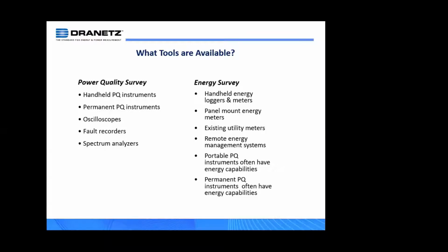And then of course when you get into permanently installed systems, now you're getting into situations where you're using remote energy management systems. And the other thing that we should note here is that we learned this in some of the early segments, that PQ instruments often have energy capabilities, simply because PQ instruments, the resolution obviously has to be fine enough to capture those power quality events, but that resolution is more than adequate for energy type applications. So you want to keep that in mind going forward.